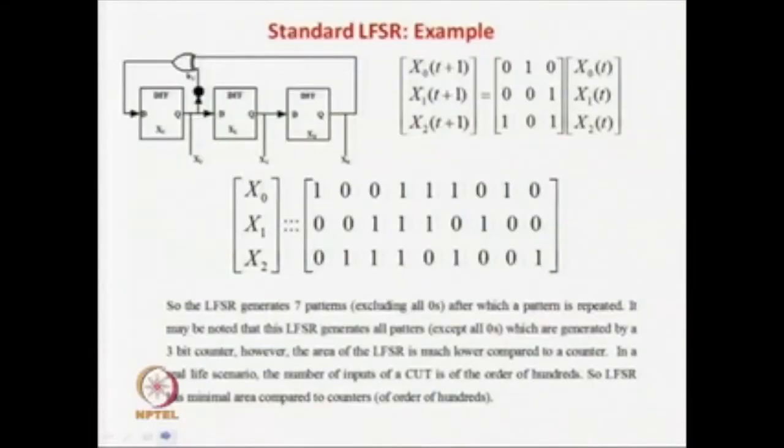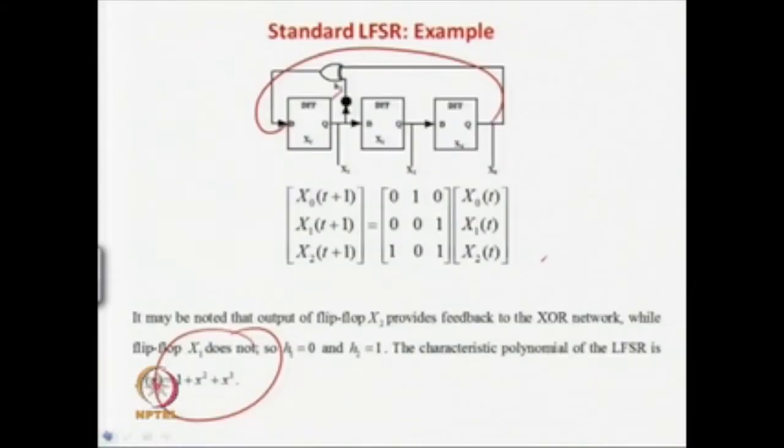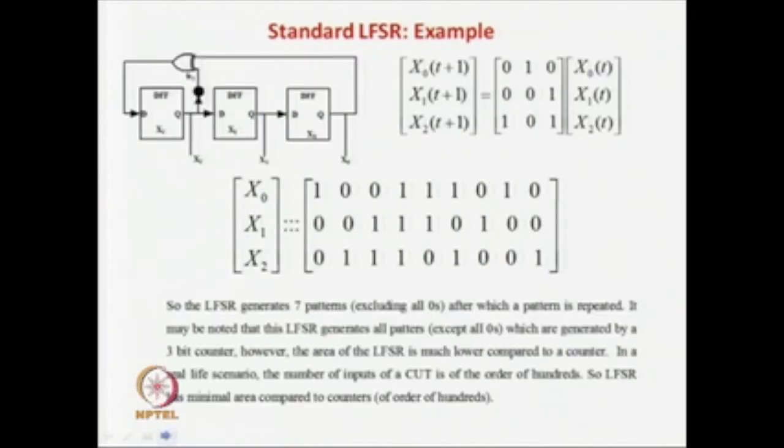Now we will go to the example. In this case, 1 plus x square plus x cube is already known to generate an exhaustive test pattern. You can easily go and find it in the list of exhaustive, near exhaustive polynomials, excepting zeros, it will generate all patterns.